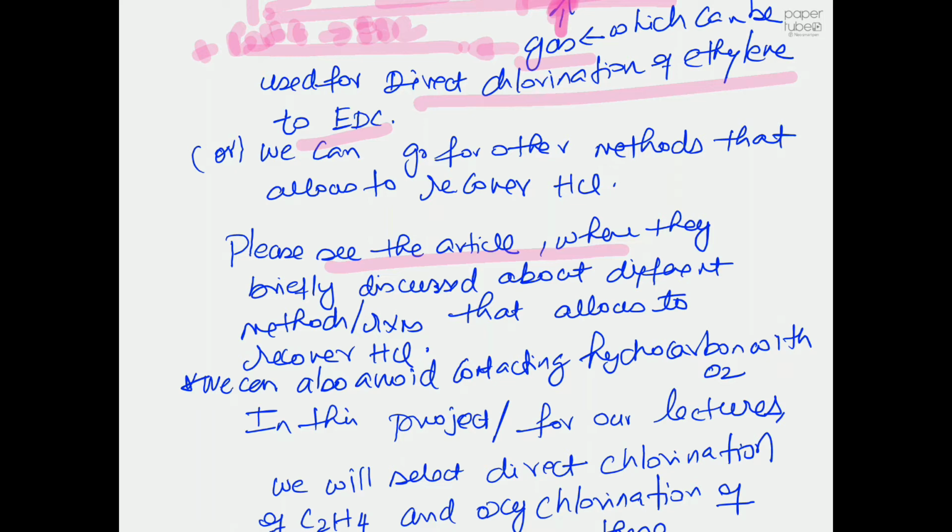In this case, we like the direct chlorination process. It's very clean, but it produces hydrochloric acid, and we are going to add the oxychlorination process because it allows you to recover that hydrochloric acid efficiently, and it also keeps the stoichiometry completely closed, which means our process is fully balanced.